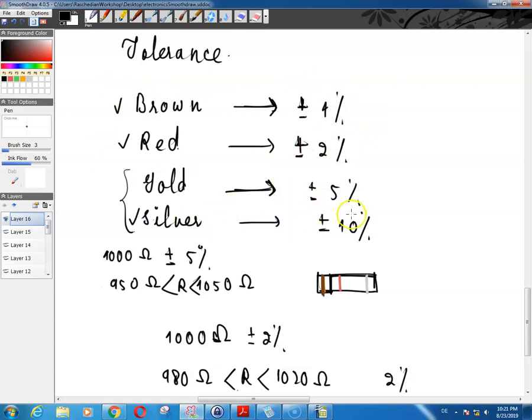For ordinary purposes you usually use a resistor which is, for example, a 10% resistor. If for a specific purpose you need a resistor which is very accurate, then you would order, for example, a couple of those resistors, and that's usually it, because these are usually very expensive compared to a 10% resistor.